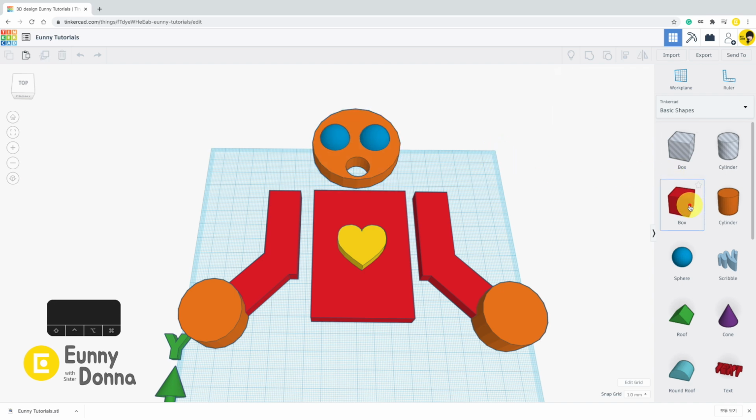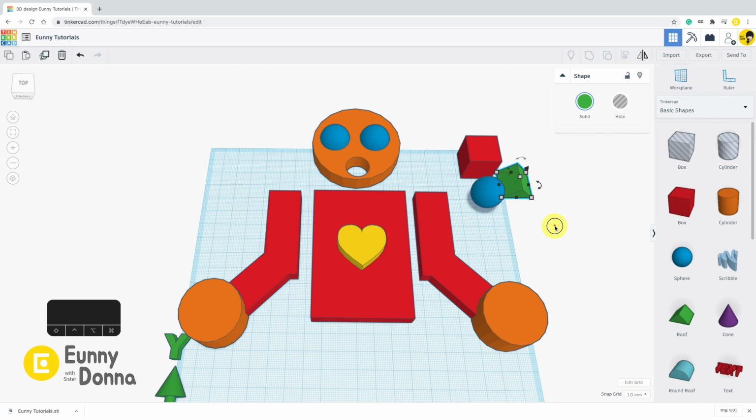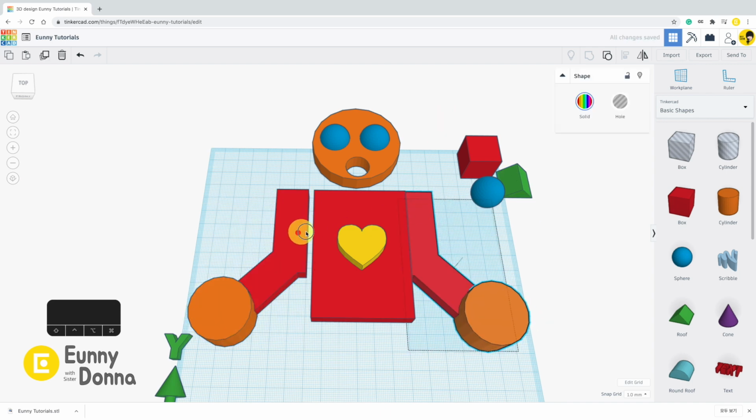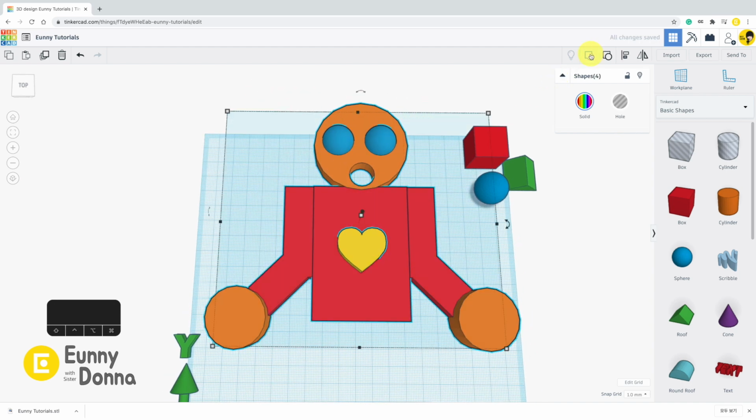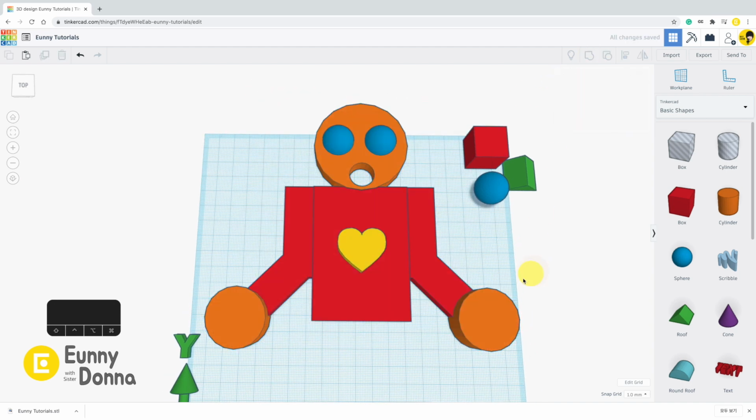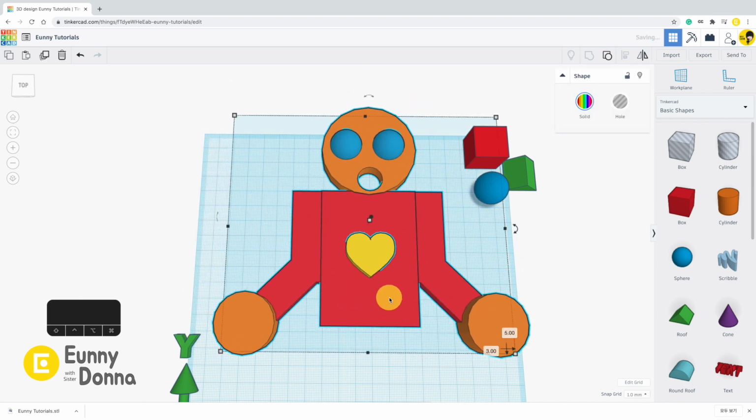But if you have some useless shapes for practice, the exported file will include those unnecessary shapes together. I believe the best way is to select the shapes you want to 3D print. Put them in a group and export this group. Now we have downloaded a STL file.